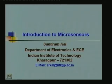The sensor is a very important device, and within a microsystem we use microsensors, and I will discuss what a microsensor is. In particular, in MEMS or microsystems we normally use semiconductor sensors. And why semiconductor sensors? Because semiconductor materials are used in many ICs and VLSI. So, if I can make the sensor out of semiconductor material, then it will be easy for us to integrate both the sensor part and the circuit part together, and that is why a lot of sensors are coming out making use of semiconductor materials.